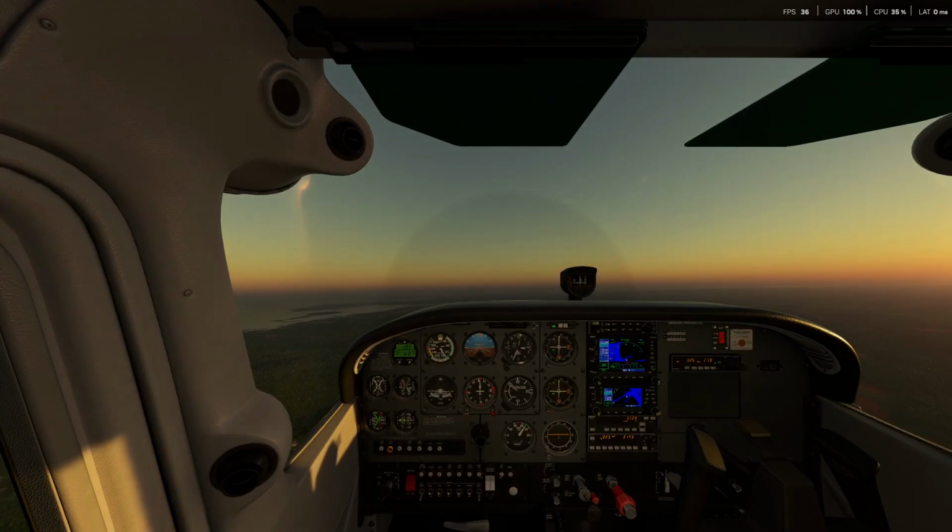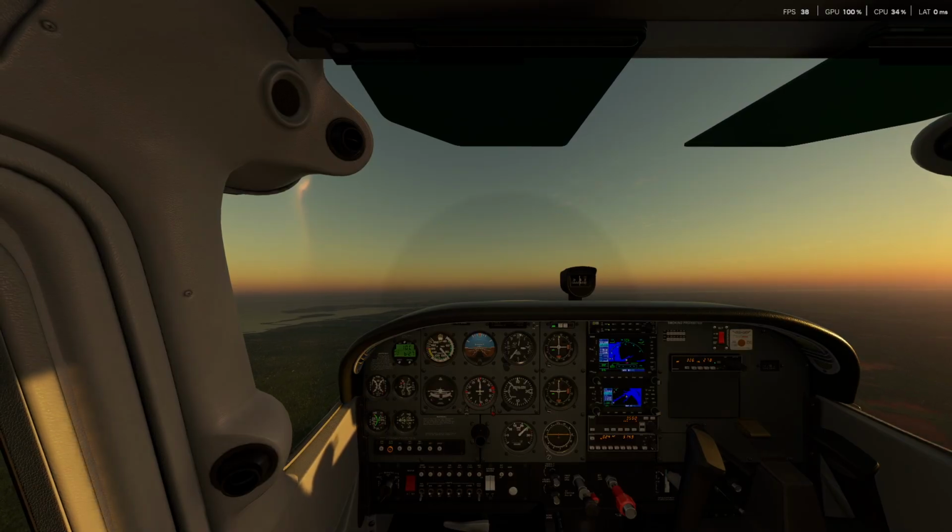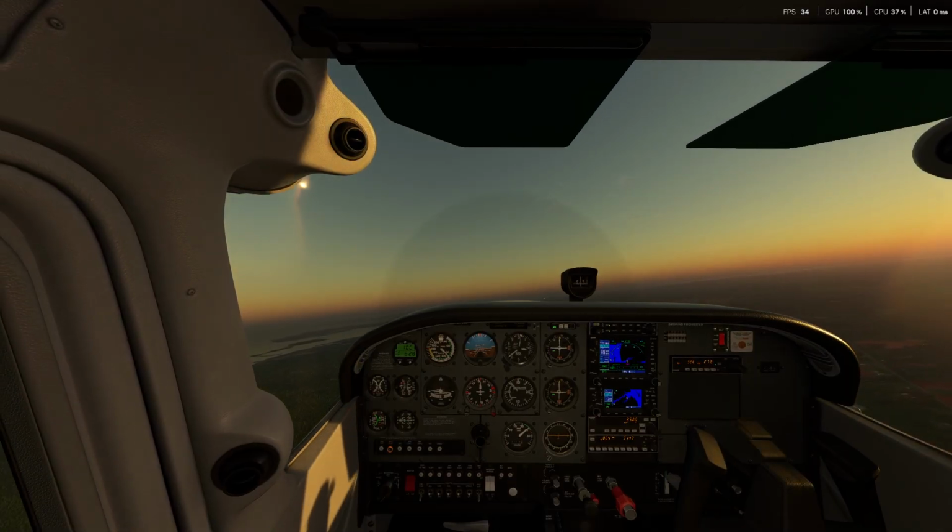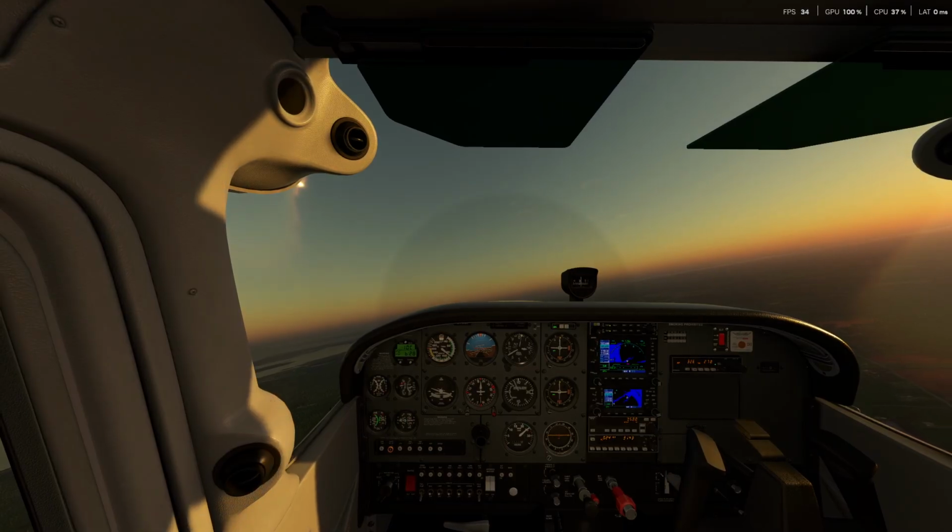We don't know what speed we want, so we'll say we want about 90 knots. So we'll go ahead and just stay at 90 knots, increase the RPM. Make the right turn, stay with the turn.